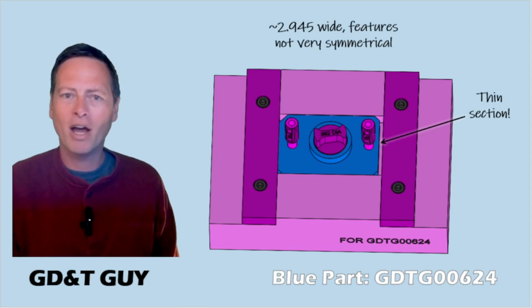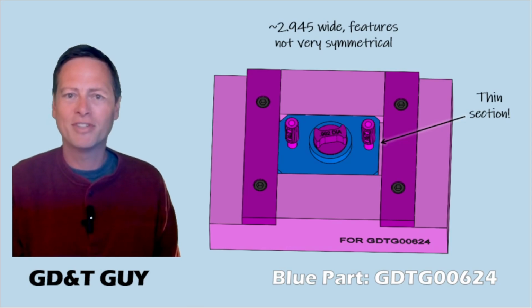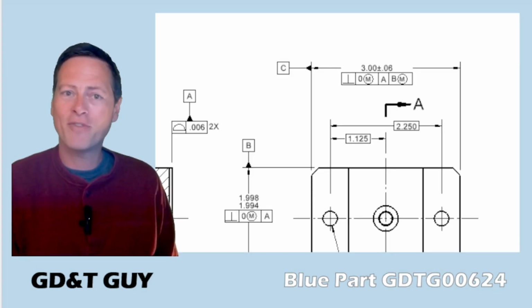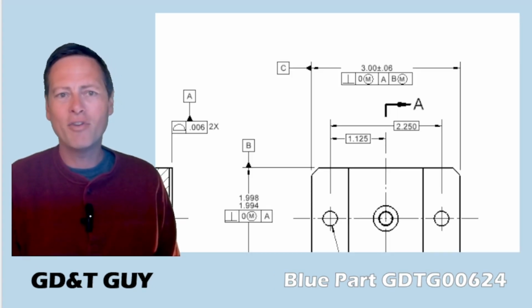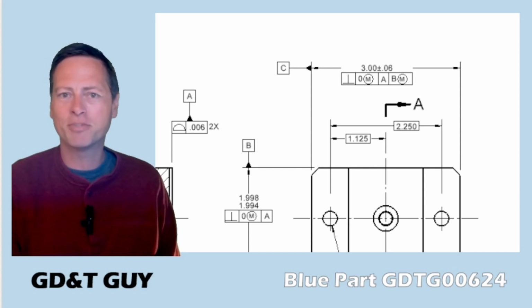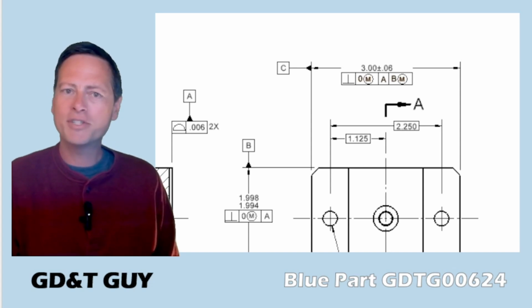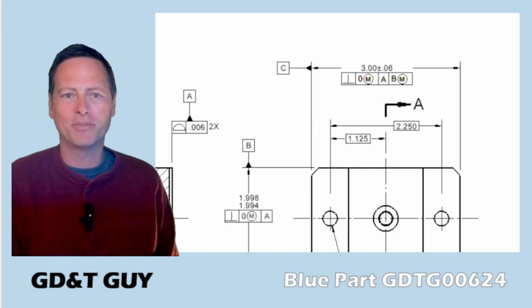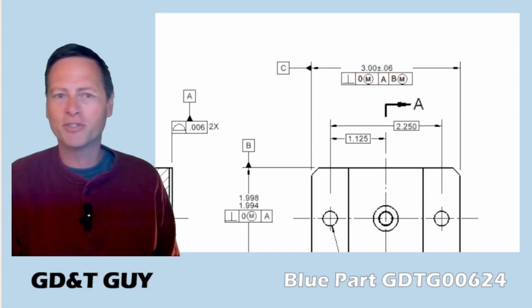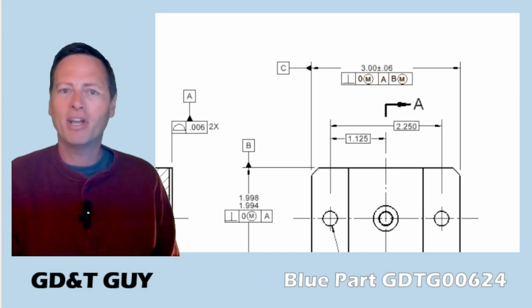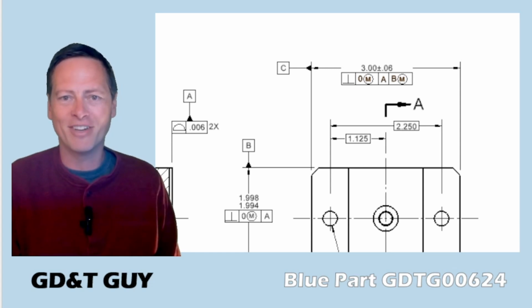As the 3-inch wide datum C feature gets smaller, the positional requirements, at least to the left and the right here, get looser. So if you are the manufacturer of this part, you have a bit of an incentive to aim a little on the small side when you produce this 3-inch datum C feature, which is kind of the way of things when it comes to MMC and MMB. The incentive is to produce features closer to LMC because the tolerances become more forgiving.